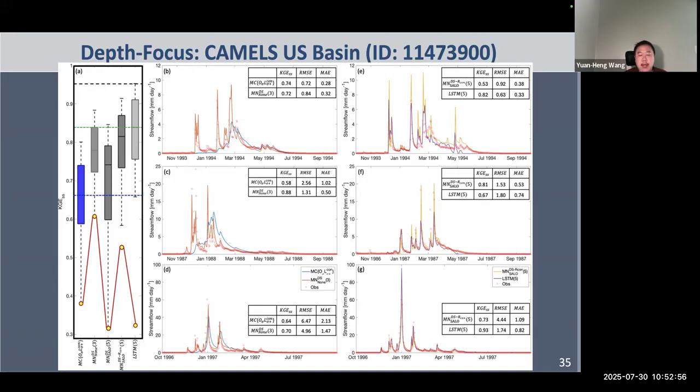But what makes me feel interested is that the single layer 3-node distributed state case without information sharing actually performs pretty well, nearly comparable to the 5-node case with information sharing and PET relaxation. So I'm guessing it's because this representation fits very properly to what is actually happening in this catchment. Maybe the 3 cell states represent snow, surface flow, and groundwater flow individually, and there is only a very minor interaction between them. So the cell state in each flow path does not affect the release of water in the other flow paths.